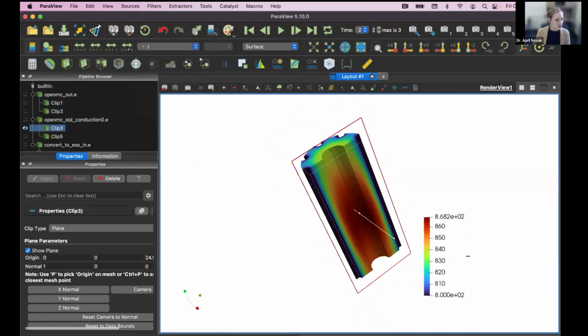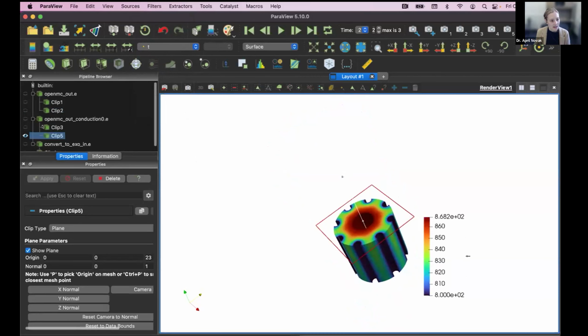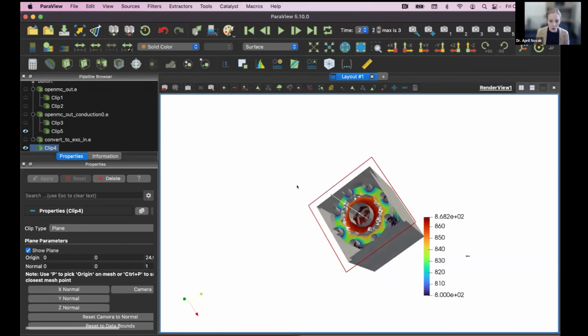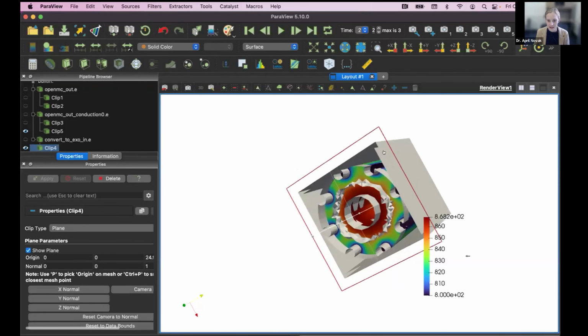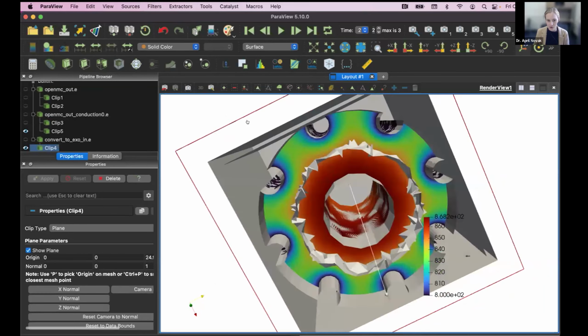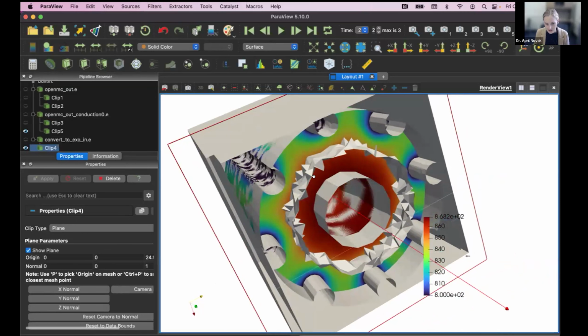If I turn back over to the temperature file and back in the fuel output file here, I can look at the OpenMC model, which is recreated on the fly. What I have here is some of that contouring opened. You can output this file with some additional settings in Cardinal. All these gray surfaces are the boundaries of the OpenMC cells that we are forming. You can see we have this new cell formed in here. That region is a lot hotter than the cell out here. Those are each going to be set to some type of constant temperature. That's fully tunable. You can control that contouring so that you can basically control how resolved the multiphysics is in a Cardinal simulation.